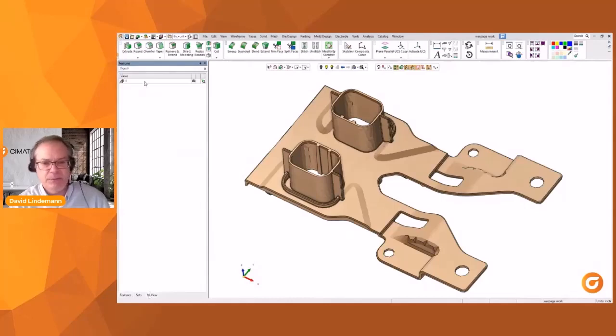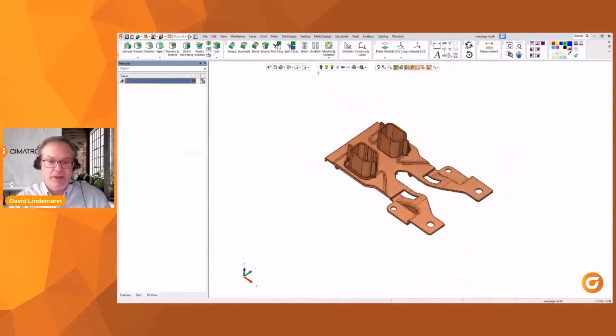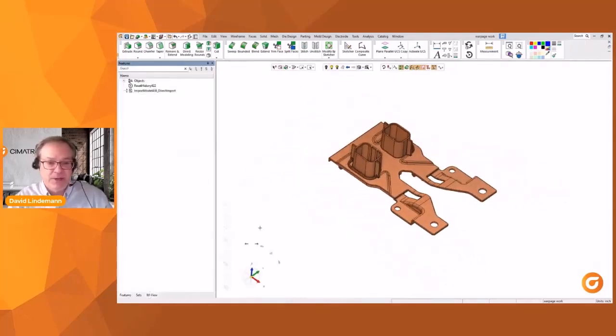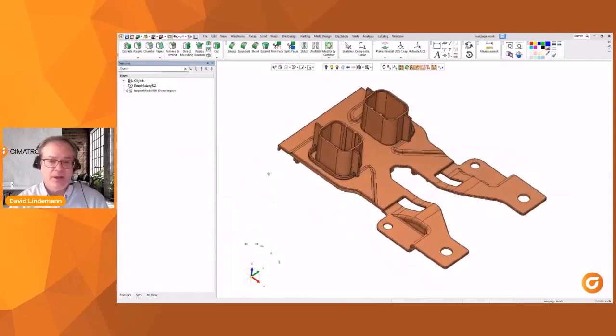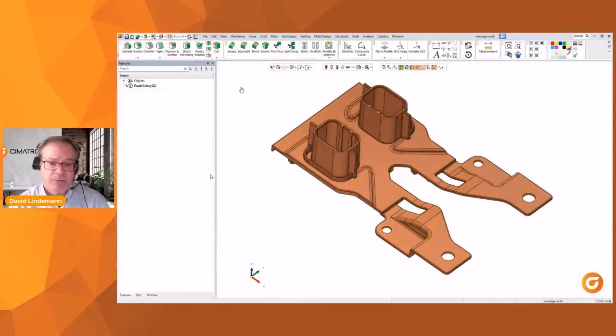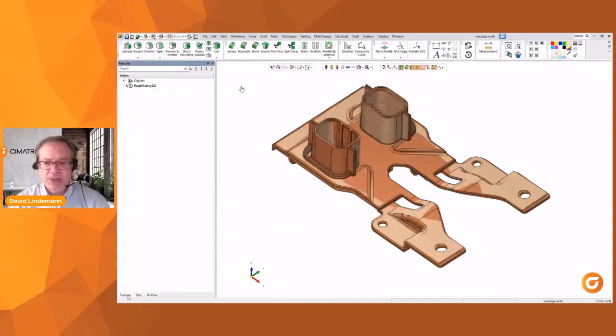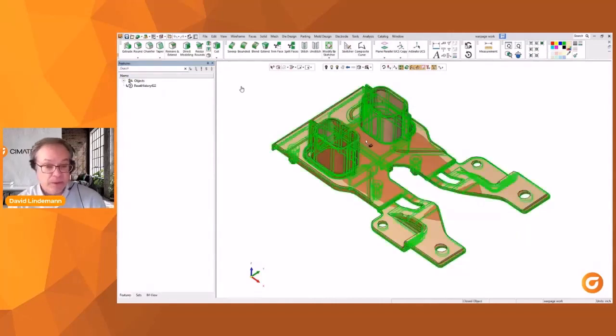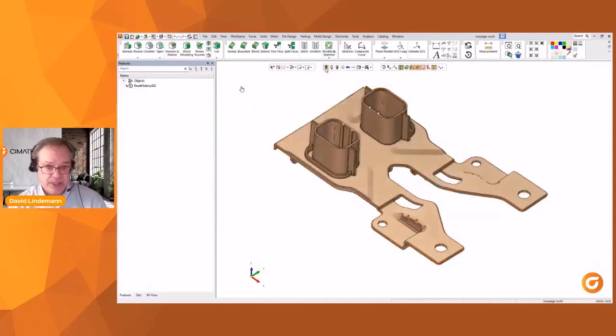Well, that's going to be typical because if I've warped it, I'm bending and bowing, and some areas that were near straight are going to go past vertical. So I will have to deal with that in order to have a moldable part. So again, here, let's look at the two, and I can see they don't quite line up even. I know that one is smaller. The STL will be smaller because the simulation has accounted for the shrinkage.